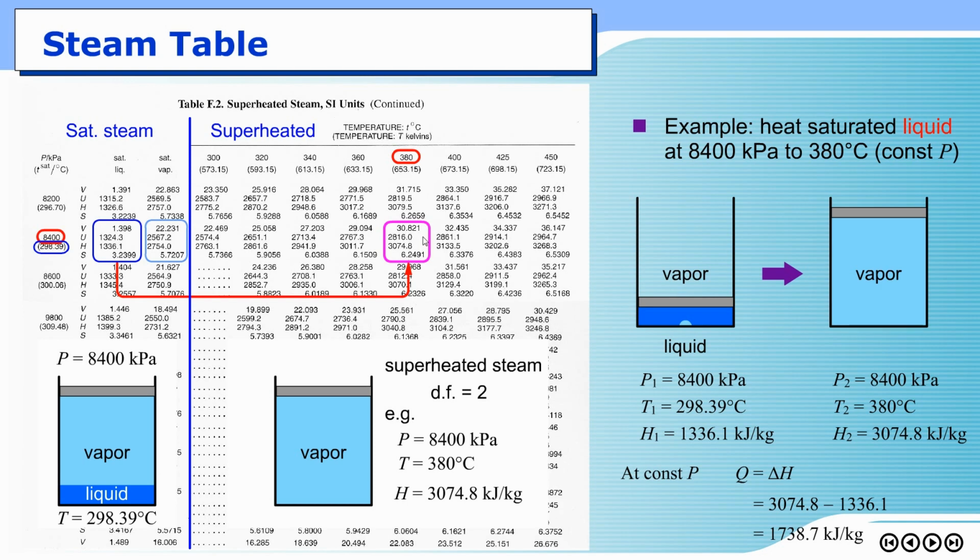Okay, but anyway, as long as you use the enthalpy data for all conditions in your calculation from the same table, it doesn't matter whether the data is a relative number or an absolute number, because you use the same reference point. So the enthalpy of the reference point would be cancelled out anyway.